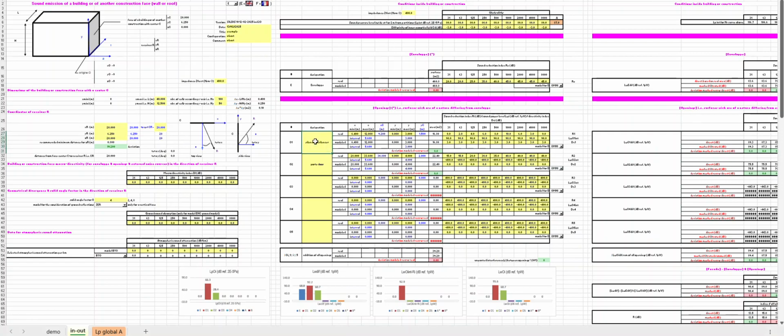For opening number 1, which is a silencer, we can account for the geometry by entering 4 distances reflecting the extremities of the surface, 2 horizontal distances and 2 vertical distances. We can enter the insertion loss of the silencer. We can also account for the sound power level of any internal additional sound source like a fan, and we can also account for a directivity term which is depending on the location of the specified reception point.